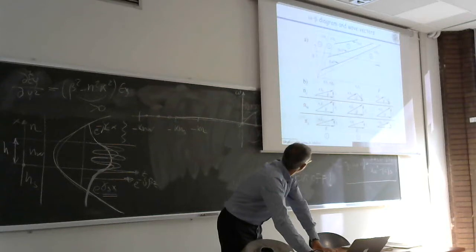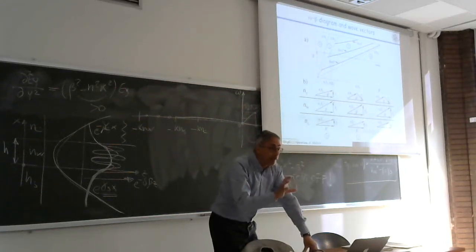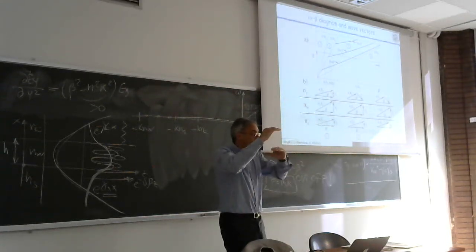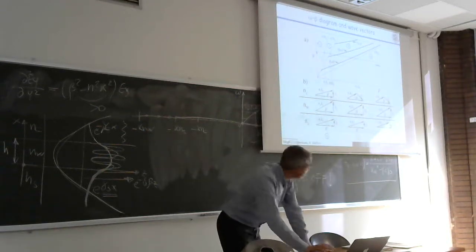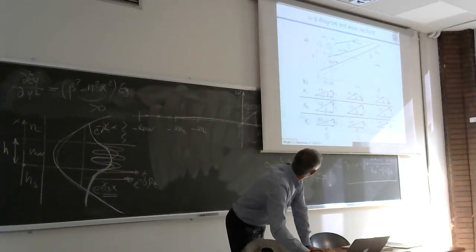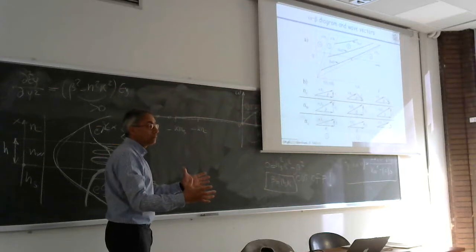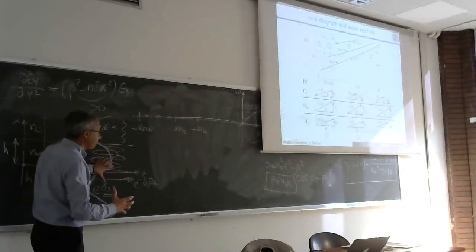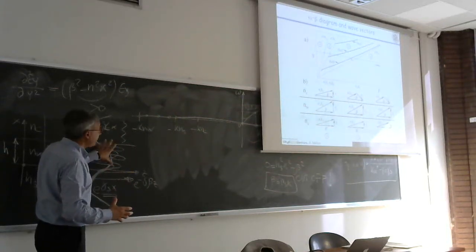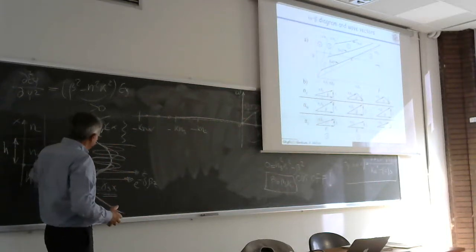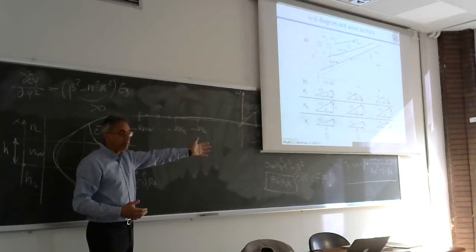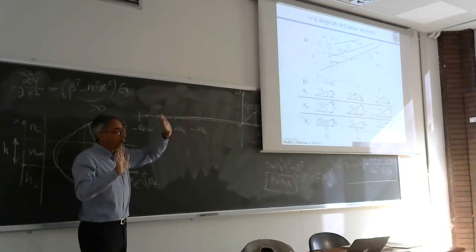So if you work at this frequency, the structure, not the material, so the thickness and the combination of refractive indices, give you two solutions, 1 and 2. So there are two modes, two configurations of field that satisfy all the conditions that we have said and that can propagate along the waveguide. And then I choose between one or the other if I want single propagation.